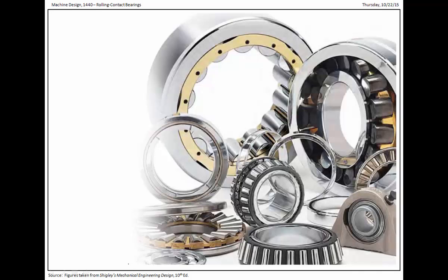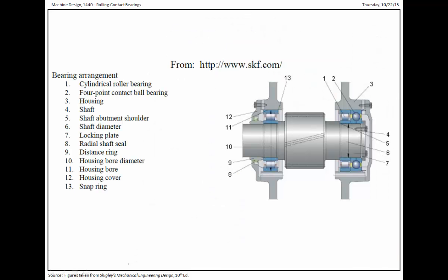We're talking about rolling bearings, which include ball bearings and roller bearings, and things like needle bearings, and a general arrangement of a shaft with bearings. We'll often see some form of way of keeping them in place with an end cap. Sometimes there'll be a Belleville spring or a series of Belleville springs, which look like concave washers, that as you apply the end cap onto there, kind of keep a positive axial load.